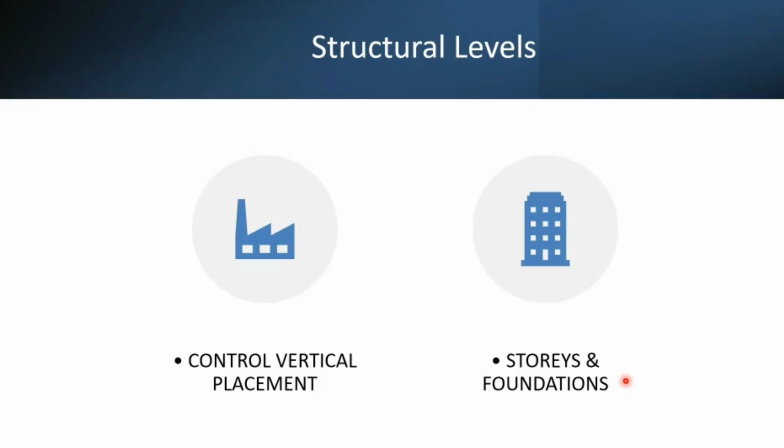Structural levels control the vertical placement and position of the structural elements, and you need to have the structural levels not just for the stories, but also for foundations, for the roofs, and for slabs in case there is necessary.